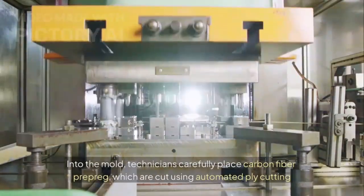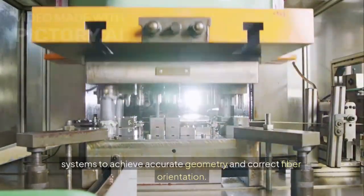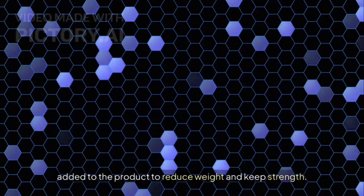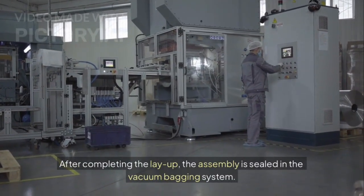Into the mold, technicians carefully place carbon fiber prepreg, which are cut using automated ply cutting systems to achieve accurate geometry and correct fiber orientation. The materials such as Nomex honeycomb need to be added to the product to reduce weight and keep strength. After completing the layup, the assembly is sealed in the vacuum bagging system.